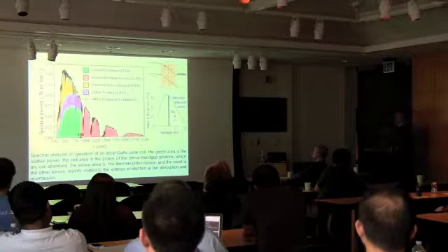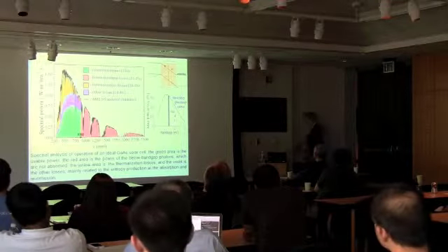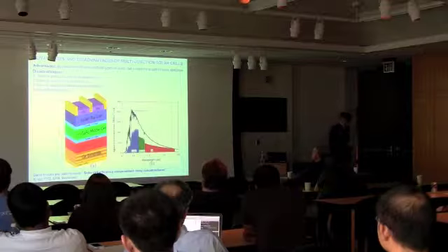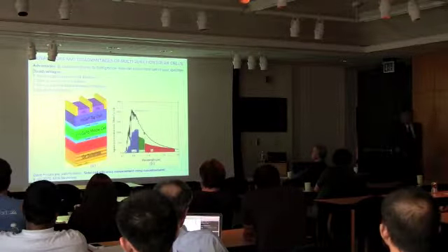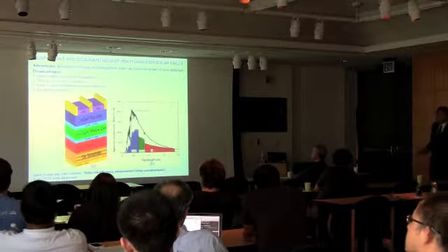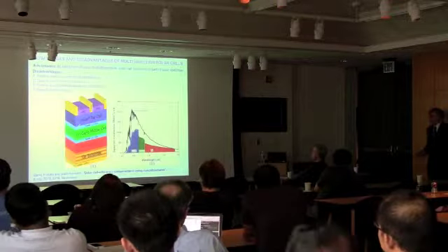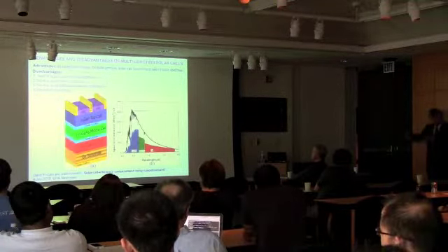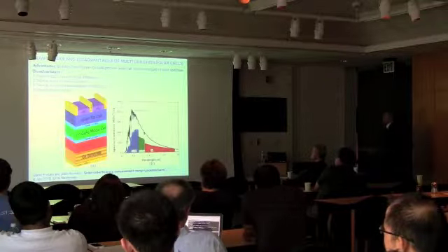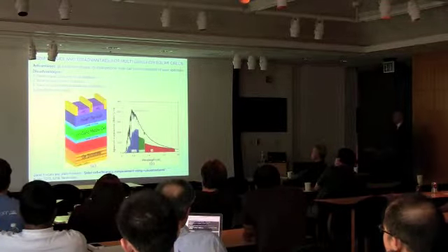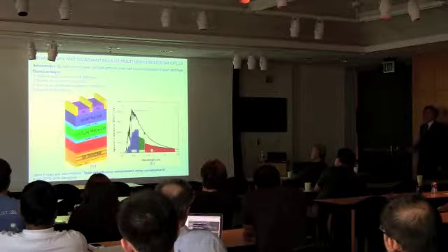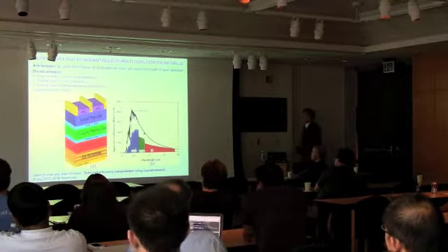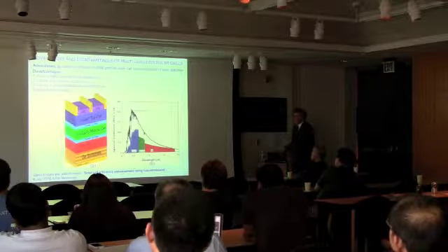So, what are the efforts to beat nature? Maybe the most successful effort is the following: if we have different materials that absorb different frequencies or different energies, let's build the tandem, or so-called multi-junction, solar cell, where the top material will have the widest band gap.